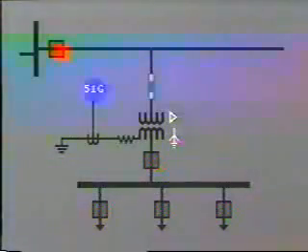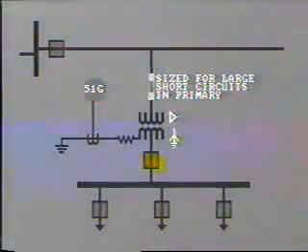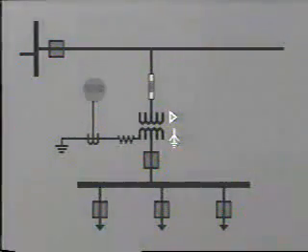The primary high-voltage fuses may not clear for a low-level fault on the secondary winding or the secondary system. They are usually sized to protect against heavy short circuits in the primary winding. Operation of the backup ground protection relays will initiate tripping of the first breaker upstream of the fuses in order to isolate the primary winding. In our example, this would require tripping of this remote circuit breaker.